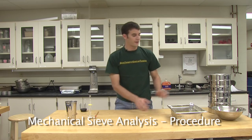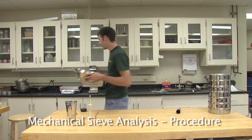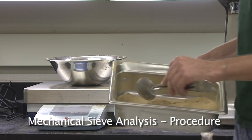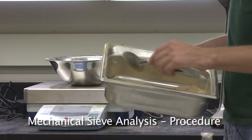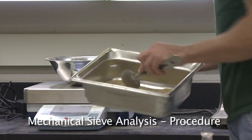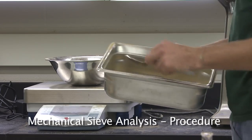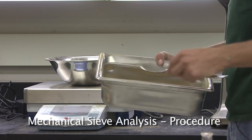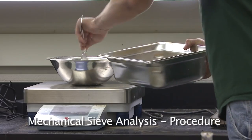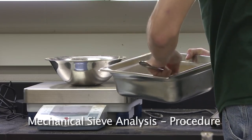Start by weighing out a 500 gram sample of the provided air-dried soil. It is important to mix the sample in between each scoop so that the 500 gram sample of soil is an accurate representation of the provided soil sample. Record the total mass on the data sheet.